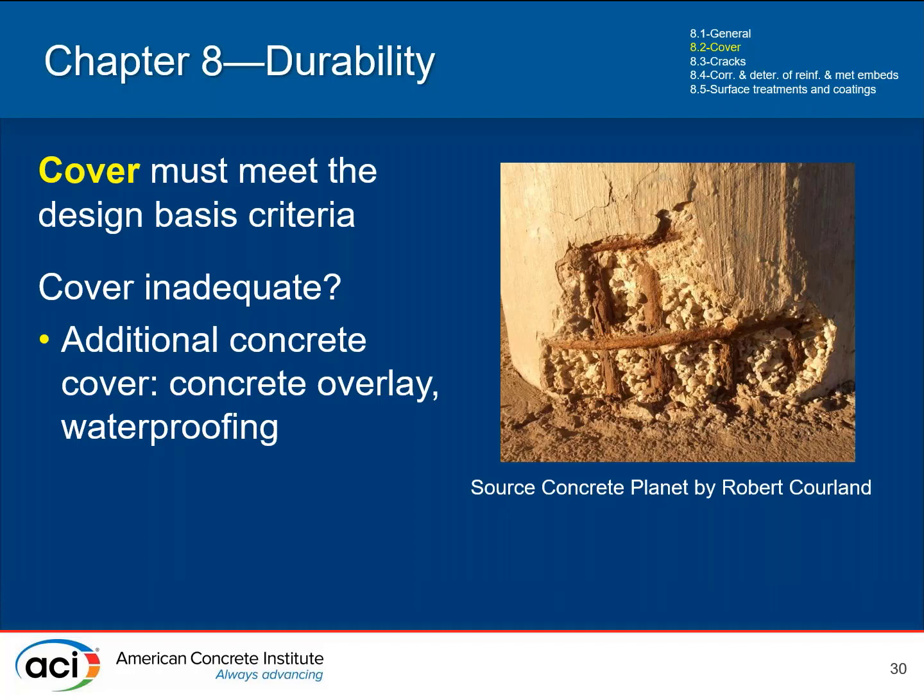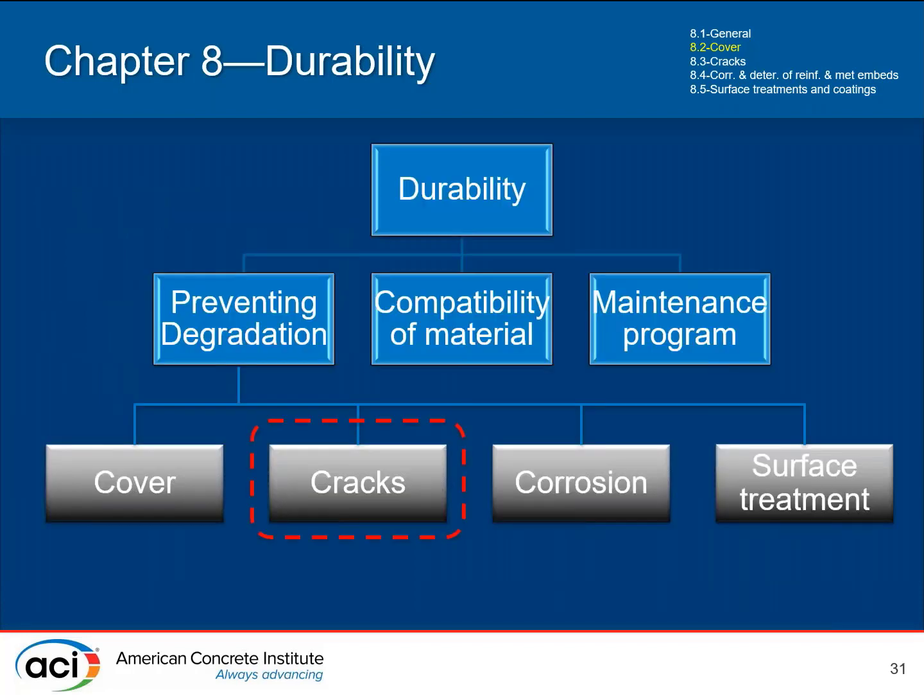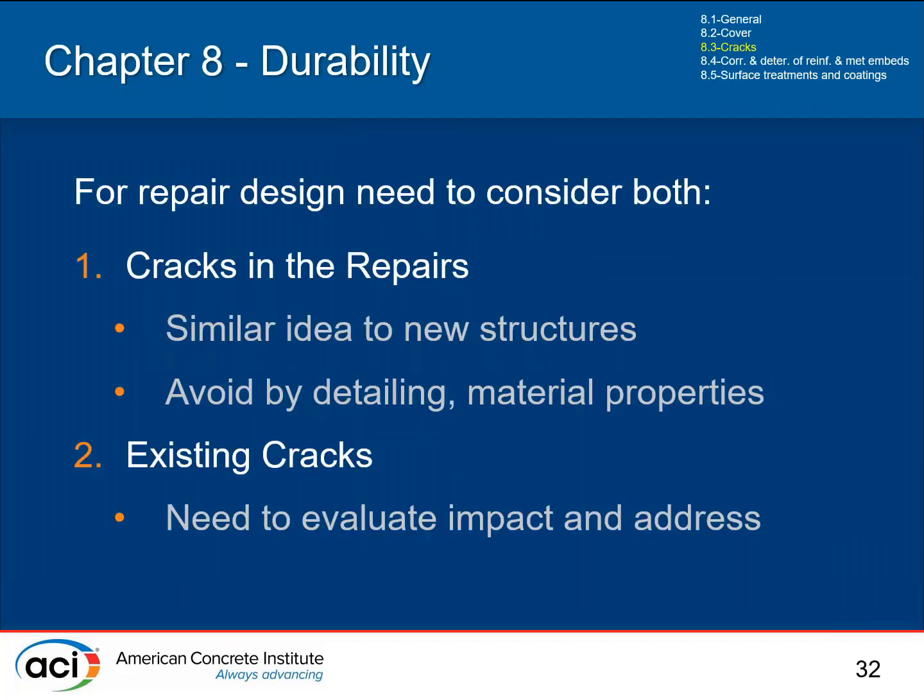But if you were looking for 2 inches of cover and you have 1.5 inches, not talking about fire or anything like that, but maybe adding that waterproofing layer is enough to consider it. Look, we have the same level of protection that the original code wanted. So we've made this repair better, and we've considered the situation, and we've done what we feel is a reasonable approach to take care of that. So that's cover. Cracks is the next one, and cracks are obviously a very important thing for durability.